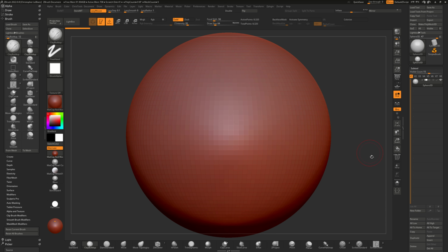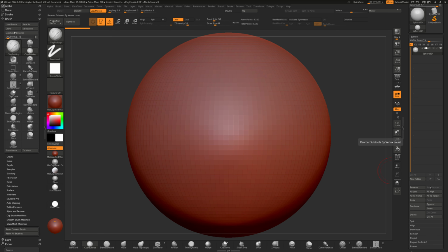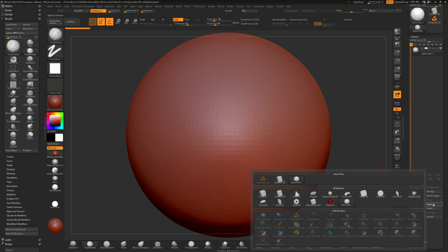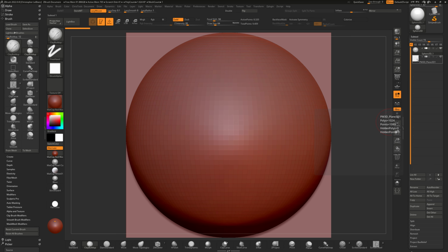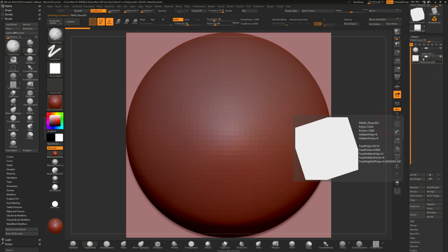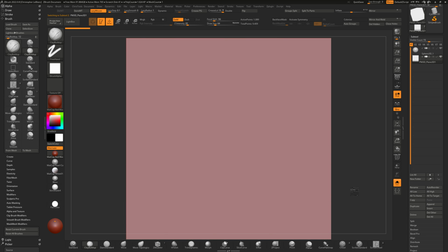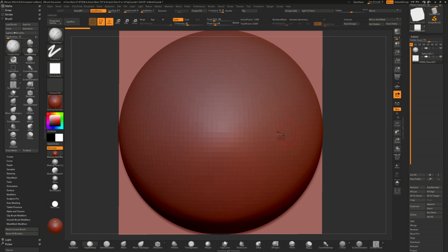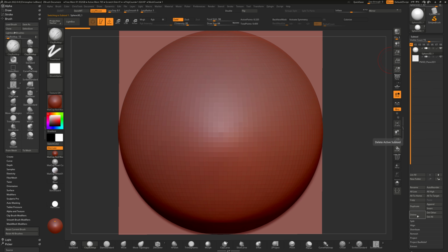First thing you should do is come over here to Subtools, and let's append using the append button here. We're going to go to Plane 3D, and that adds it underneath here. Select it to make it the active subtool, and we can solo it if you're feeling lazy, or for the sake of the tutorial, we'll come up here and we'll delete the sphere out.